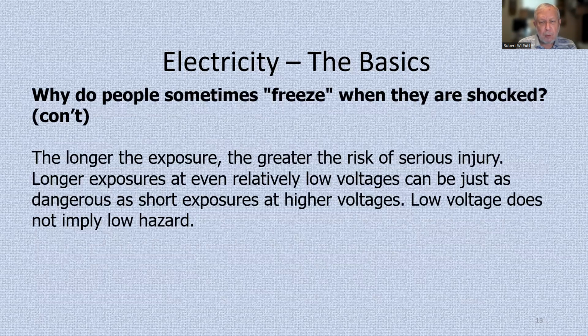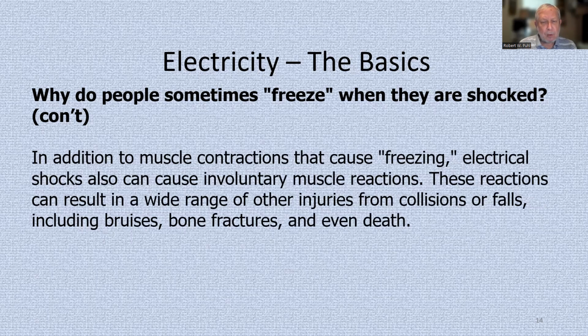The longer the exposure, the greater the risk of serious injury. Longer exposures at even relatively low voltages can be just as dangerous as short exposures at high voltages. Low voltage does not imply low hazard. In addition to muscle contractions that cause freezing, electrical shocks also can cause involuntary muscle reactions. These reactions can result in a wide range of other injuries from collisions or falls, including bruises, bone fractures, and even death.